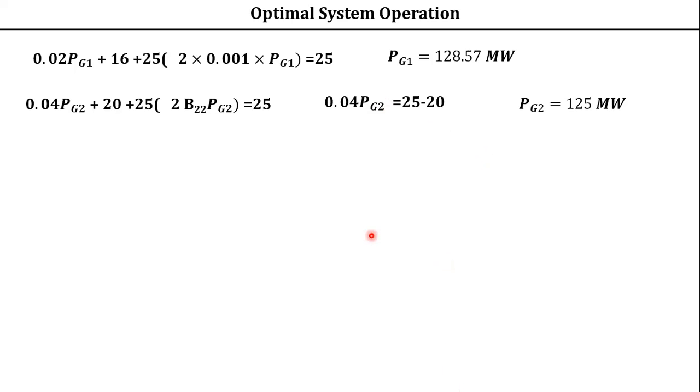So you can see here, PL is equal to 16.53 megawatt. Let us check the values they have given, whether it is right or not. PL, the transmission loss, is equal to B11 into PG1 square. B11 is 0.01, PG1 is 128.57. I think other answers I have already shown here. 237.04, Tushar has given. Now here you see this one. This is the total loss now.